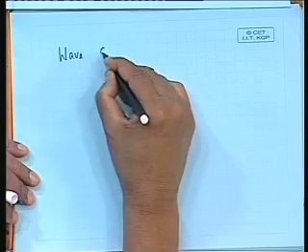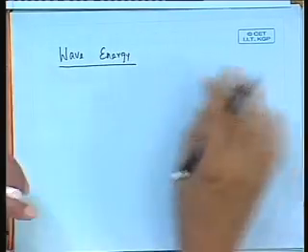Okay. Now I'll talk quickly about an important concept called wave energy. Energy becomes important because ultimately, when a ship is trying to move, like with wave resistance, which you have seen, Professor Misra would have done it, when the ship moves in water, it makes waves. Okay, where does it come from? It has been made by the ship. But why do you say it is a loss? That's the physics behind it. Why do you say that there is a loss of energy? Let the wave be made. The question is, why is it that you need some force to make those waves?